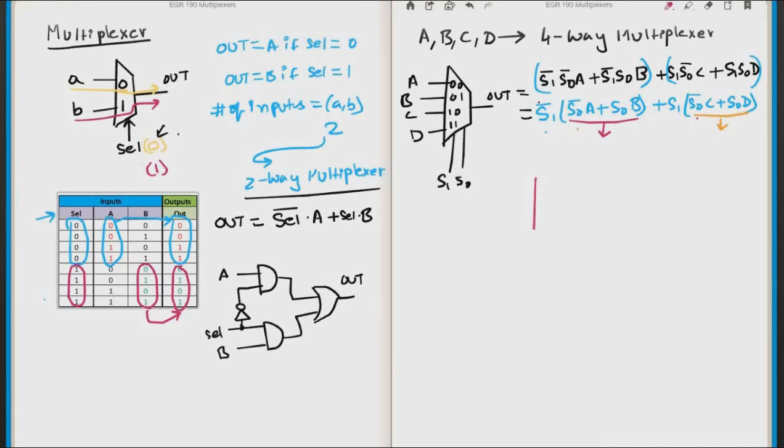So let's look here. I have a 2-way multiplexer with select S0, inputs 0 and 1, and I connect A and B here. Similarly, I have another multiplexer with input S0, the same input, so I'm going to take that and connect it here, and C and D go to 0 and 1. I have 2 outputs coming out. So you implemented these functions using 2-way multiplexers.